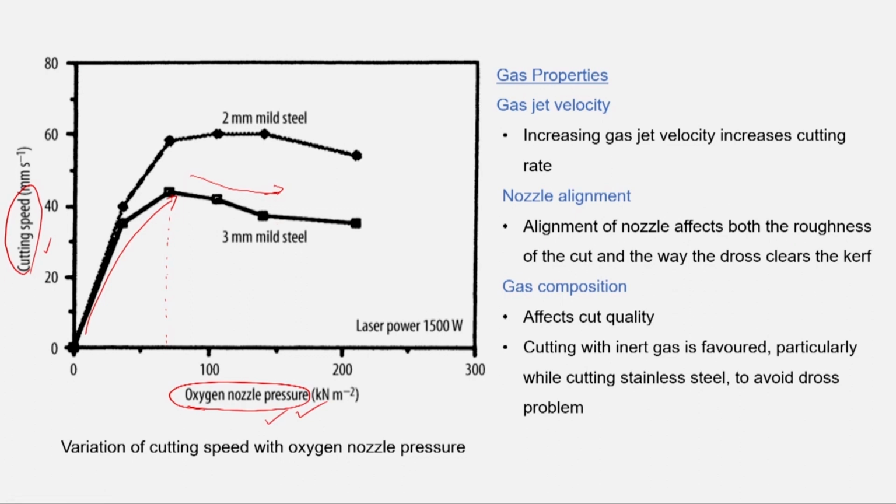It is due to the pressure which we are applying by the oxygen. It is interfering with the laser material interaction, and it is not helping for the efficient material interaction. It is disturbing the material interaction. We are using oxygen for extra input, but the pressure that we are applying of the oxygen is not helping to get the required cutting done.